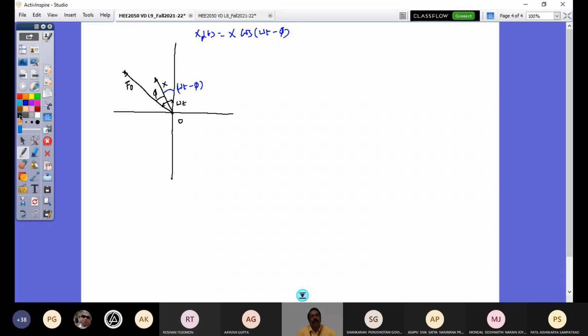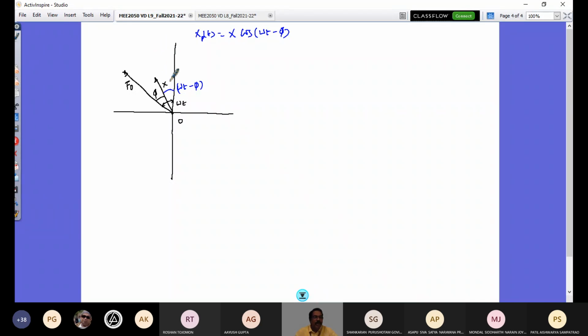So now, because of this displacement, what you have is this force k times x. So this is my dynamic displacement, and I have my stiffness. So that would be k times x. It is in line, and this is my kx vector. And I would have my c omega x vector comes like this. This is my c omega x. And I would have my inertia vector comes like this. That is m omega squared x.